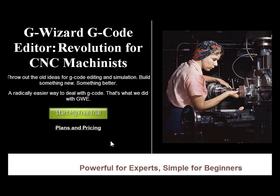So I know somebody's probably thinking, hey, my CAM program has a simulator built into it. What do I need this thing for? I always do a simulation before I run it on the machine. And the answer is CAM software, for the most part, uses a simulator that doesn't work from your G-code. What it works from is the geometry, the model that's inside the CAM software.